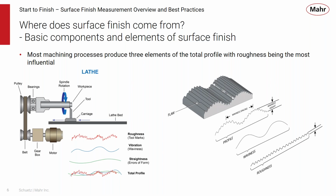And all those really become a fingerprint on the part. So here's the example of the tool marks, the vibrations, which cause waviness, and long-term straightness errors or form errors that can be imprinted on the part. All those things give us a total profile, and they can be separated out by different types of filters, but roughness is the one that most importantly affects what we're trying to measure in a part, and that's what we're going to talk about mostly today.